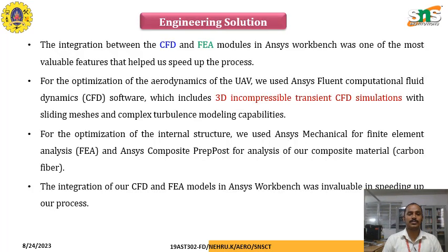The engineering solution they arrived at: the integration between the CFD and FEA models in Ansys Workbench was one of the most valuable features that helped speed up the process, especially the computational fluid and structure interaction done using the Ansys software. For the optimization of the aerodynamics of the unmanned aerial vehicle, they used Ansys Computational Fluid Dynamics software, which included 3D incompressible transient CFD simulation with sliding meshes and complex turbulence modeling capabilities.